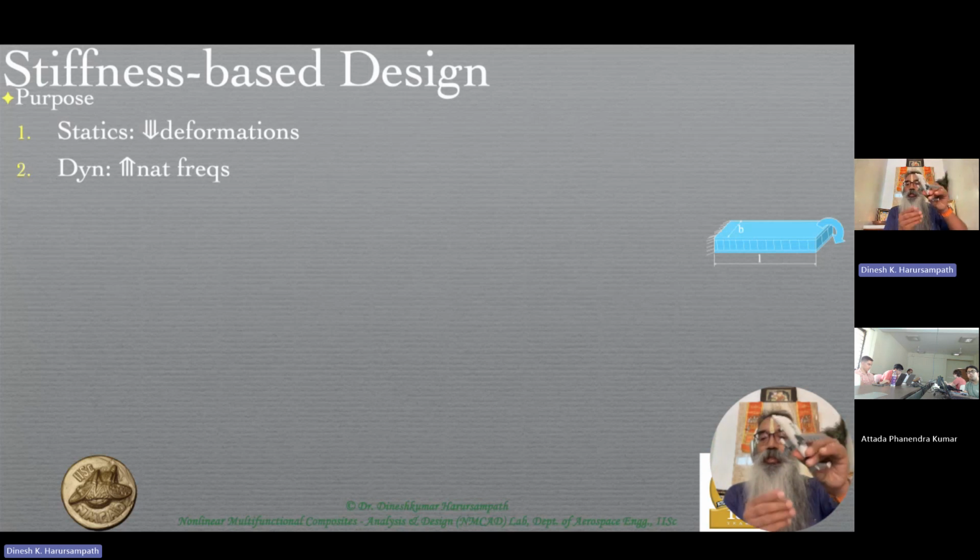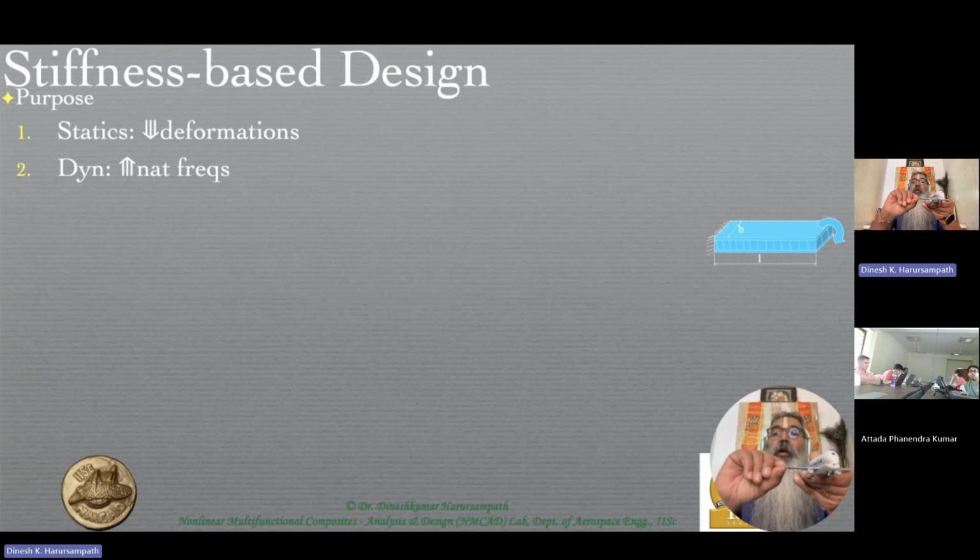So if you take this wing, for example, it can go up or down. That's essentially bending. It can go forward or backward, which is much more predominant in the case of the helicopter, but here also because of the drag, which we call the lead lag. This is called the flapping degree of freedom in the case of the helicopter. This is called the lead lag. And then you would have the torsion. So these are all the kinds of curvatures that result because of the moments. Two of them are bending moments due to lift and drag. The other is the torsion due to the pitching moment, which will twist this entire structure, right?